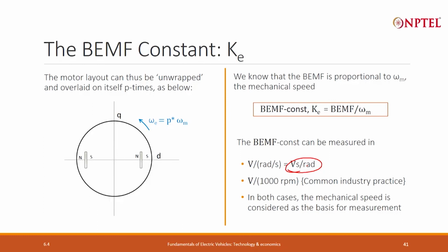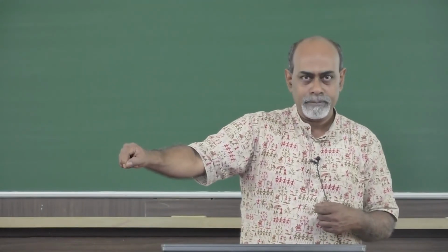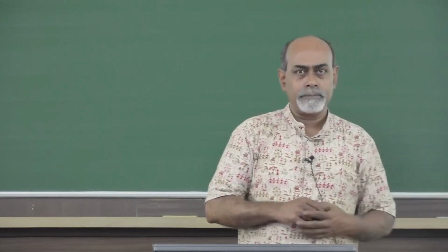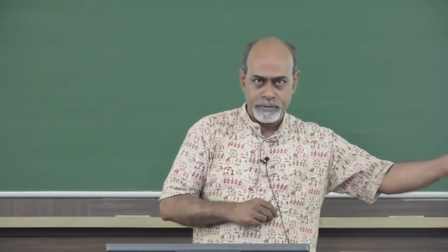Any doubts? If you have no doubts, I will give you an assignment. It has been a conventional industry practice, because when I want to rotate it, I do not literally do it with my hand. I will couple it with some other motor which will be running at a known speed, and I will measure the back EMF.